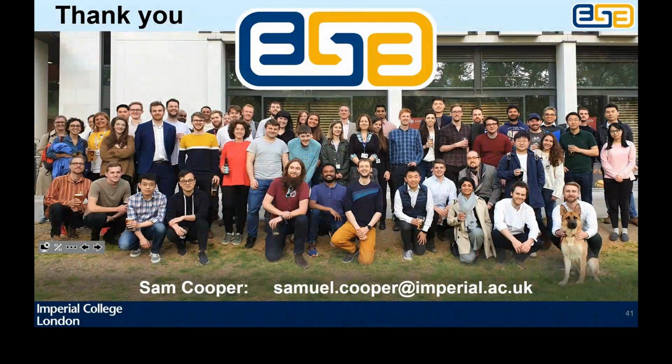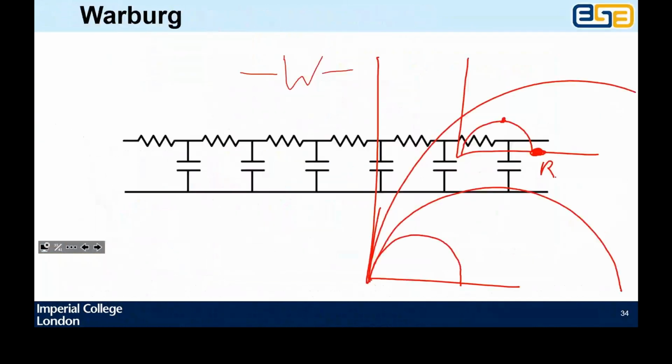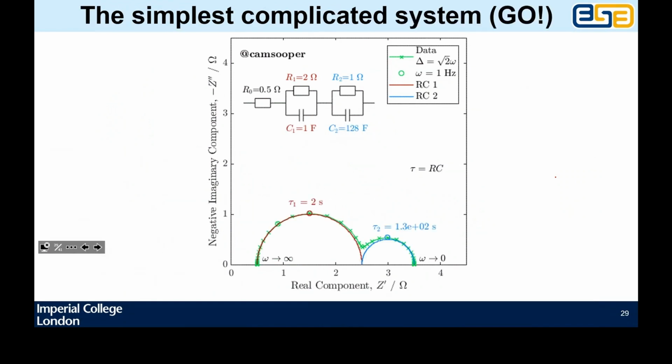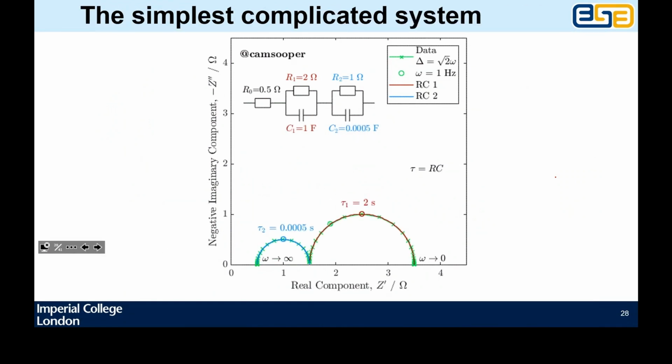Good point. So there are 4 different Bode plots you could have. All of them have frequency or maybe log frequency as their horizontal axis. You can have 4 different vertical axes: real, imaginary, magnitude, and phase angle. For each green cross, for this particular frequency here, there is the magnitude, which is the length of the line connecting that.